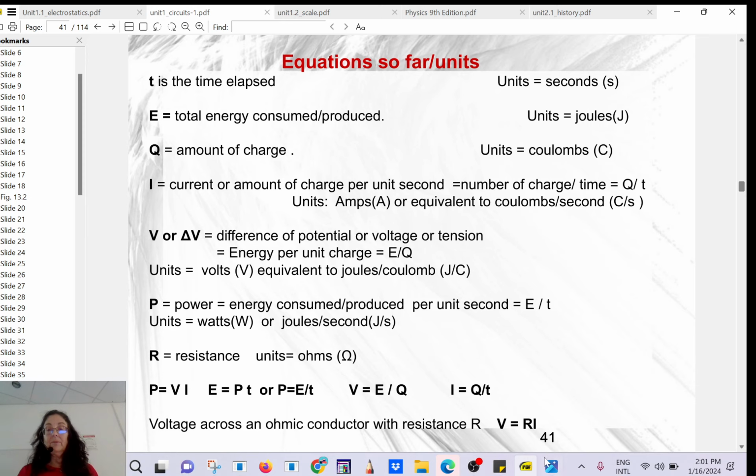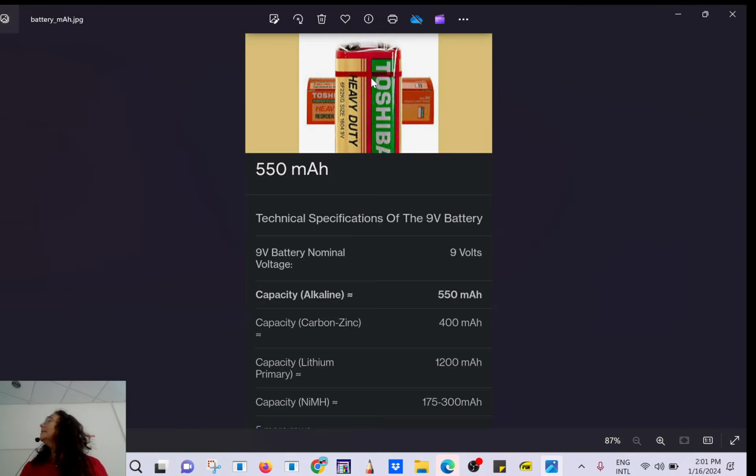For example, if you have a 9-volt battery here, you have a positive terminal and a negative terminal. The positive terminal will be 9 volts relative to the negative terminal. You can think of the negative terminal as being the ground. You can think this is 0 and that will be 9 volts. So voltage, actually voltage drop, is a property of two points.